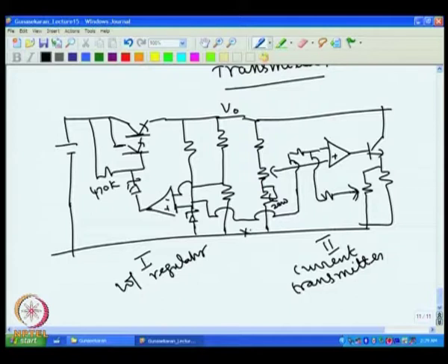Typically we get 0 to say 7 volt here, fixed, and this 7 volt is determined by this V reference and these two resistances, say R10 and R11. So, R10, R11 and V reference form this 7 volt, because we know the voltage at this point is 5 volt, and the voltage across this is 5 volt. So, you can adjust R10 to get whatever voltage you want.